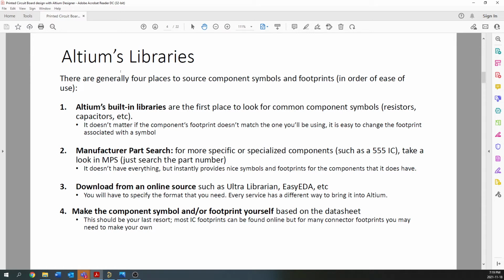There's maybe 30 or 40 different footprints out there that most diodes, transistors, microprocessors, and specialized chips use. They all use relatively the same footprints, and they're widely available. Connectors are not like that. For a million different connectors, you're going to have a million different footprints, and those are most likely not going to be available for some more esoteric ones.